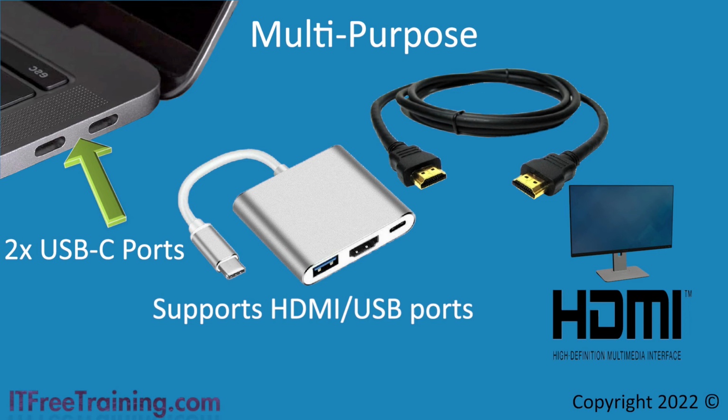Keep in mind that there are a limited number of wires in a USB-C cable, and thus the amount of data that can be transferred is also limited. If you start connecting multiple devices together, your experience may be affected by how much data is transferred through the cable. Although technologies like Thunderbolt and DisplayPort allow multiple monitors to be daisy-chained together, keep in mind that if you